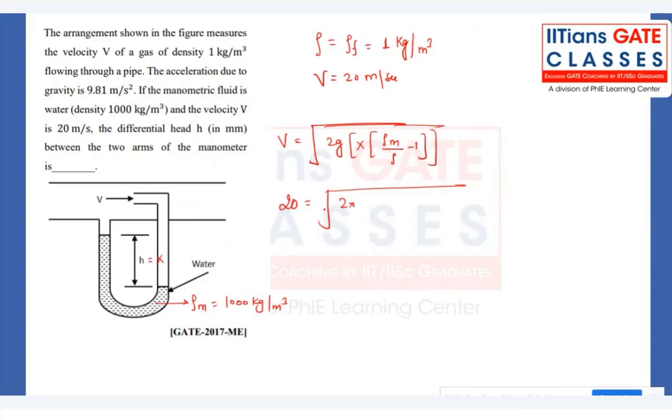Now, is anyone getting a doubt? I will come to that doubt. X is what we have to calculate, and rho m is 1000, minus 1. So 20 squared equals 2 into 9.81 into 999 into x. If you calculate the value, you will get x as approximately 20.41 mm.